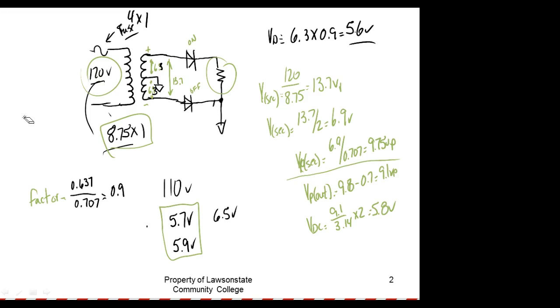So if you ever get to a building, it's up on the power poles, it's going to be single-phase transformers. If it's the utility's, I mean, it's going to be 3 single-phase transformers wired as 3-phase. But if you get into the commercial building, odds are it's going to be a single 3-phase transformer. Their transformer. So it depends on who the transformer belongs to. So that's a pretty neat thing, right?